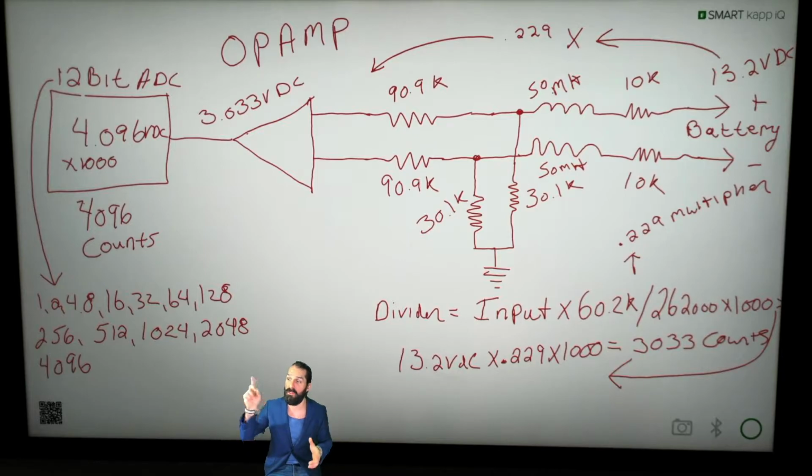So what we're going to look at first today, and I just drew up this little circuit, is the importance of divider circuits and monitoring systems all throughout data centers and critical infrastructure. Now, divider circuits are very, very important depending on the analog to digital converter. New type ADC systems will have 16 to 24-bit analog to digital converters. The reason that's important is because they'll have a max ceiling on the digital bits input that they can have.